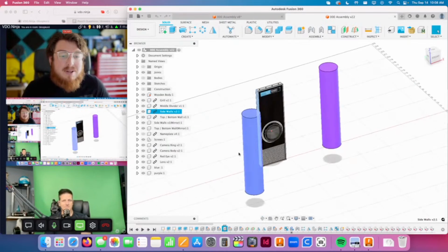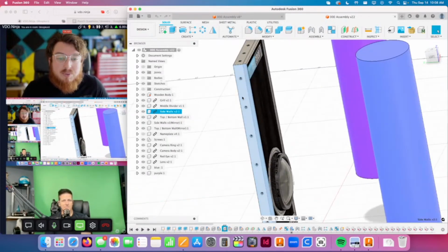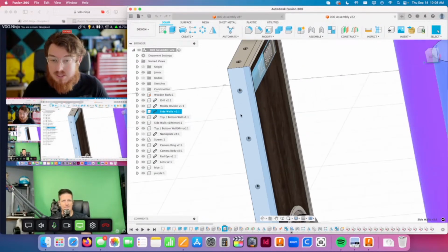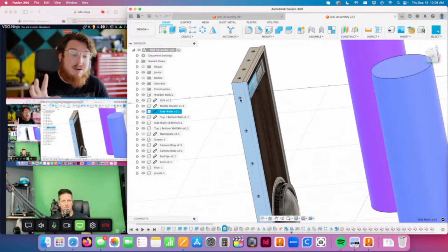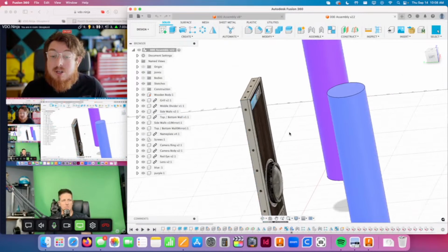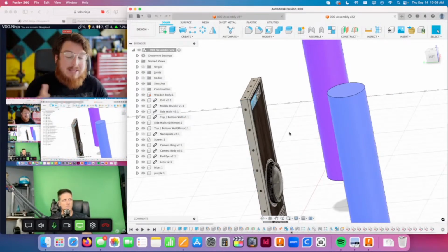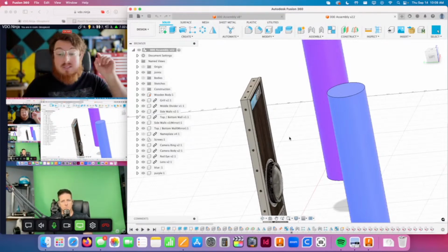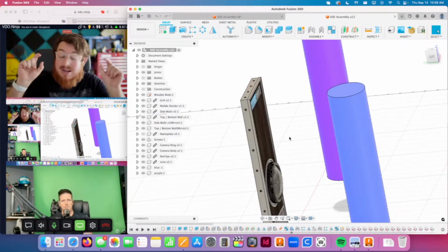So we've got a row of bolts all the way down the side. This is a sketch that we've extruded some holes into. Actually, no, this is a pattern from the hole tool, where we've added a bunch of holes. Anytime you're looking at a pattern like that, when you go into the sketch workspace, it's going to add a little icon, in the same way it does for any constraints. If you want to see tangent or horizontal, it's going to add all these icons on there. You can click them and delete them.